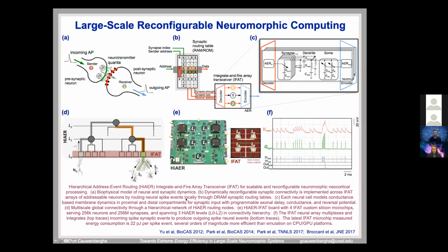Right? And the efficiency of that representation here: you do this analog compute for the neural integration, this two compartment model, so you have a soma and a distant part, and synapses and dendrites are represented here in analog. But then when it spikes, it sends out an event, and the event goes through this system around it. You go through memory tables that figure out the synaptic input going to some other neurons, and perhaps neurons elsewhere in other systems, through this HiAER framework. It's all great, but the efficiency that we accomplish here is about 22 picojoules per synaptic event. And so how can you do better?